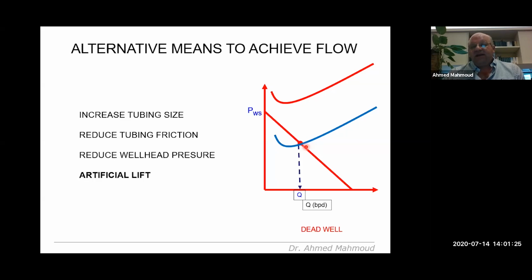Obviously, you know the depth of your well, you will draw your curves as I did in my previous example. And from there on, this is what will dictate the total number of valves you need. So that's for the first part of the question. Now, for the second part of the question, where are these gas lift valves located? So typically these valves are seated inside a housing, which is called a gas lift mandrel. And within this gas lift mandrel, the valve goes in and sits, all right? And this mandrel is installed, okay?